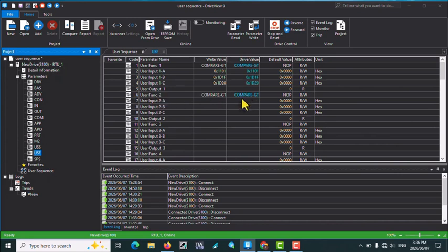We said that we want our inverter to stop if the frequency value drops below 5. So we need to assign the constant value 1 to the output of this function, which is the inverter's hex address. We mentioned that if we send the value 1 to the inverter's hex address, the inverter will stop. All right, let's go.